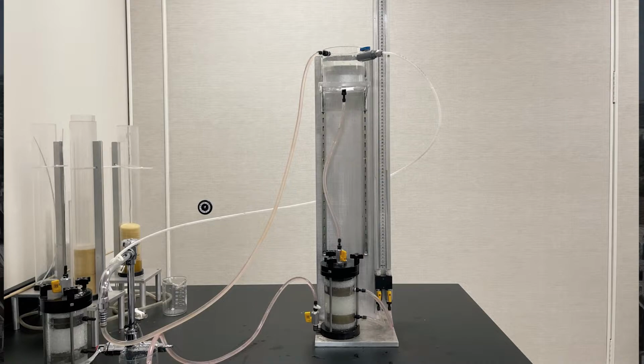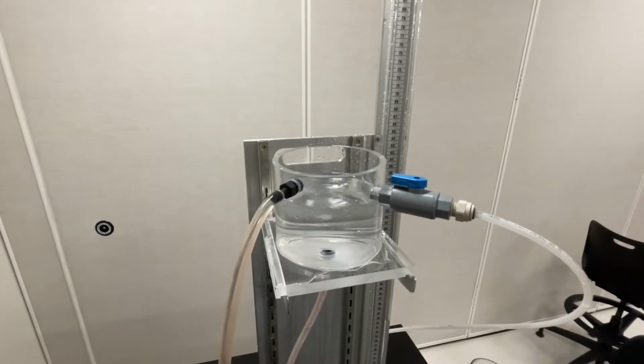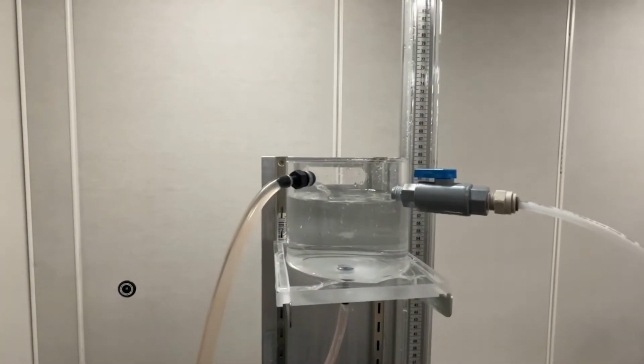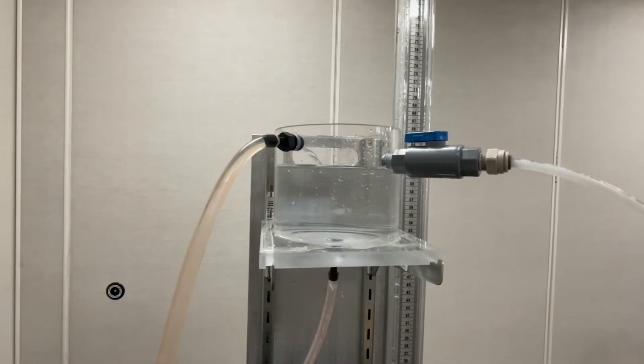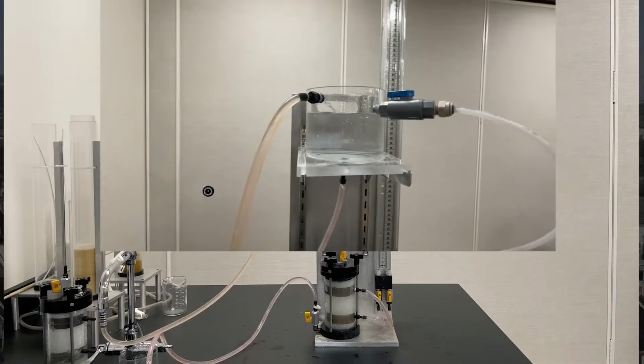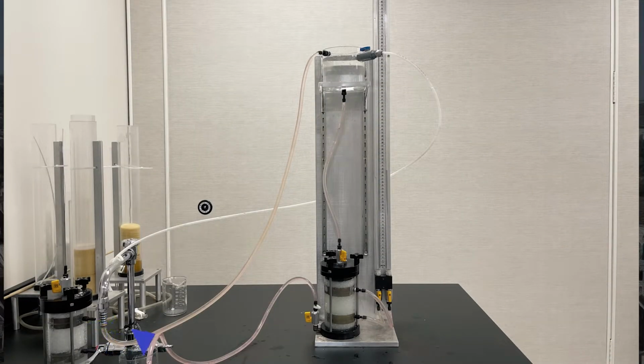Water is fed into the Darcy tube via a constant head tank to overcome Darcy's problem of variation in inlet pressure. This tank provides a consistent source of water at a steady pressure head and without introducing air bubbles into the system. A tube from the water source, in this case a lab faucet, flows into the tank, while a bleed-off tube ensures that the tank does not overflow.